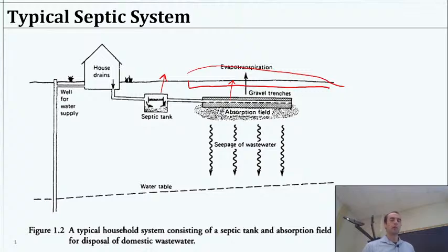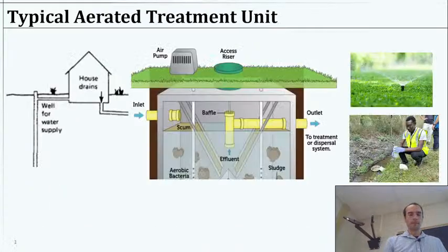So that's one option, and that's something that we were actually recommending to the group in Nicaragua, that perhaps making a bed over the septic field, raising the bathrooms a little bit, might help with some of these cases where the groundwater is too high during the wet season. So that might be a thing.